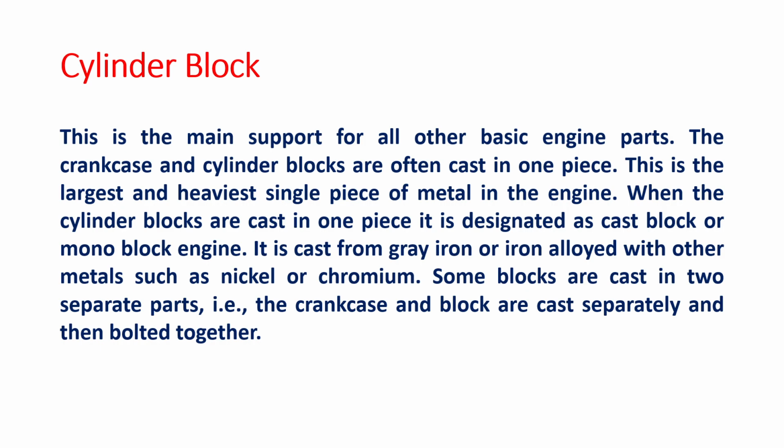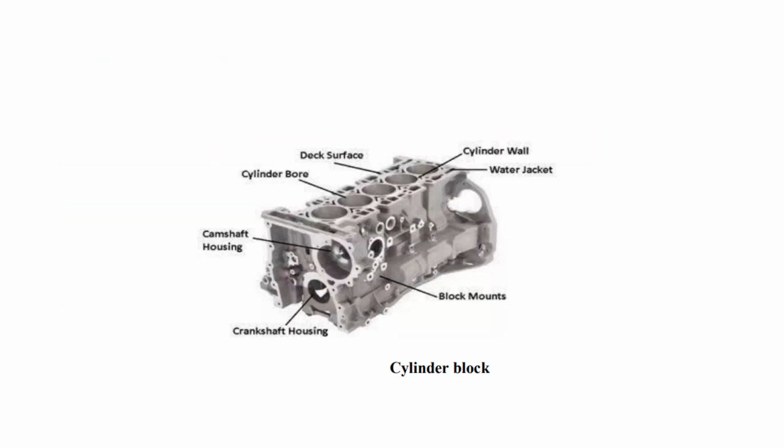The first part, I can depict in this diagram. You can see that you have a cylinder for your camshaft housing, block mounts, a cylinder wall, the water jacket for cooling, and also a deck surface. First I'll go for the materials that are used, and the casting is normally intricate. The passageways are also provided to accommodate the valve mechanisms.